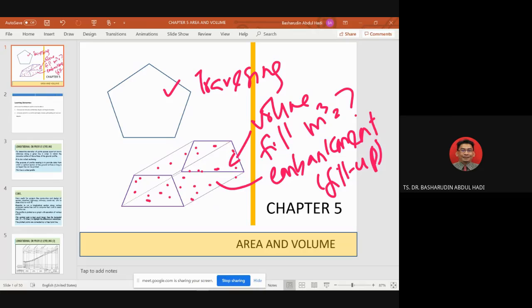For the road construction, it is not right to put the road at the same level as the paddy field, because the water will rise. Even though we are doing embankment, with a low embankment sometimes the area floods. So you have flash floods sometimes. So you must put up a lot of fill. This area is a very huge embankment to make sure our area is safe from the water level.